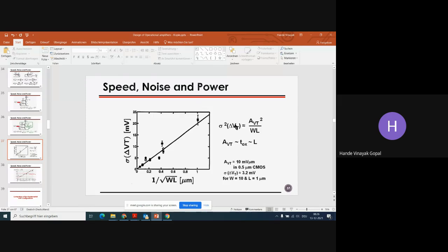the spread. At the end, what I wanted is to reduce the spread of the threshold voltage, or sigma of the threshold voltage variations. I can do it another way by increasing the W. But the problem with area increment is that you will reduce the speed and all. But generally in sensor based applications, we don't care that much about the speed. If I wanted to design the circuit for sensors, then definitely I can increase the area. Yeah, please go ahead.